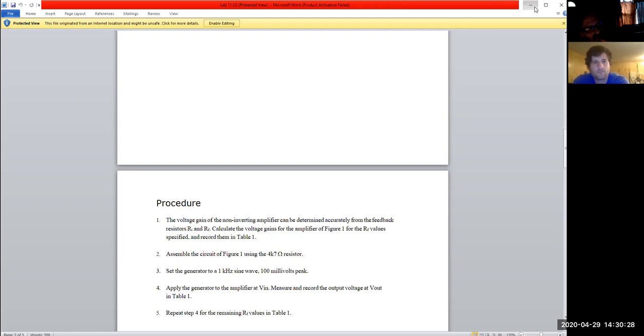So whenever you powered off one machine somewhere down the line, it would make enough ground bounce to interfere with our other machine. So we had to start sending those things out with noise filters on the inputs, like these big honking iron ferrite bead coil things. We called it our Asian rework, because of their horrible power out there.